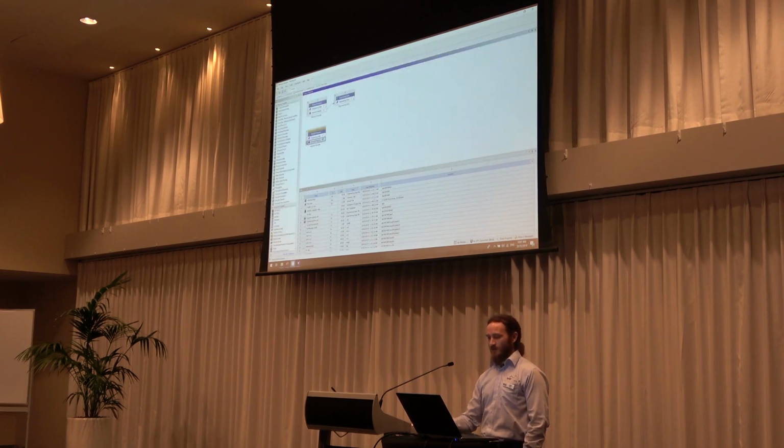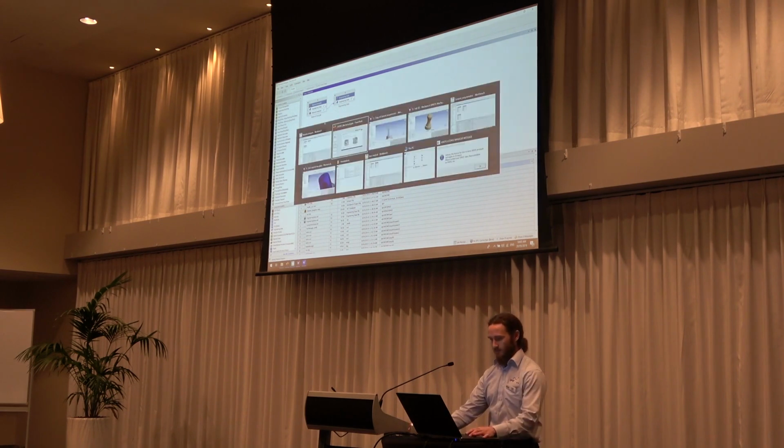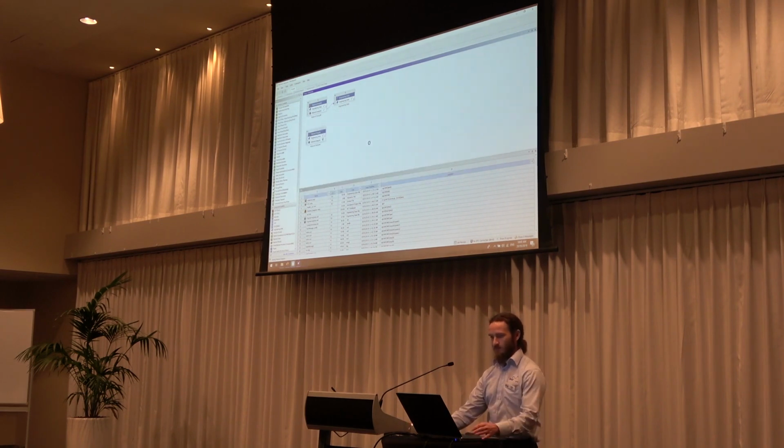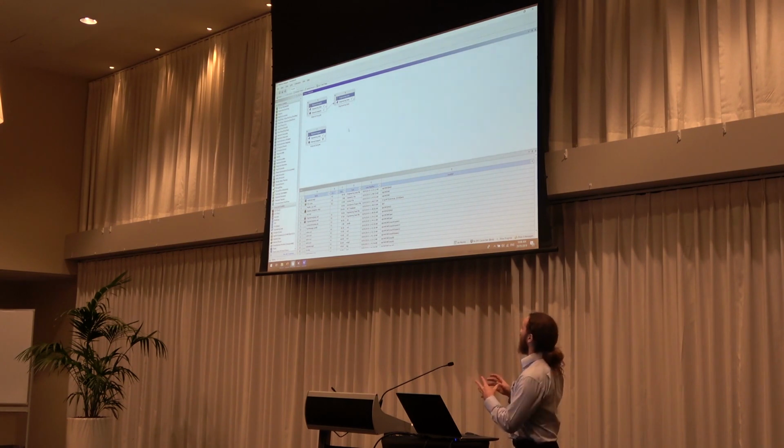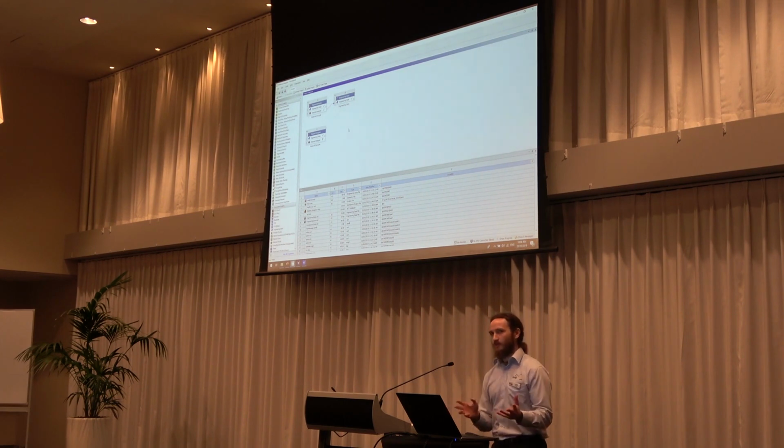Now I go into Material Designer. So this is in the SpaceClaim interface, which is nice. So it's really easy to use. So it's basically a tool that automatically generates the geometry for, I think I have a license warning. There we go. Yeah, it automatically generates geometry that represents a unit cell for our composite material, and then it meshes that, runs an FE simulation, and then extracts the orthotropic material properties for that, and then feeds that into engineering data, and then we can do a simulation with a proper composite layup.